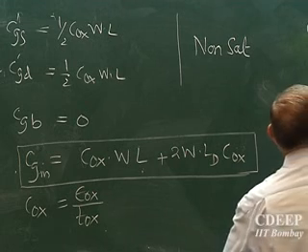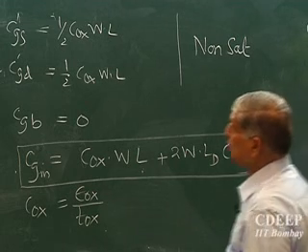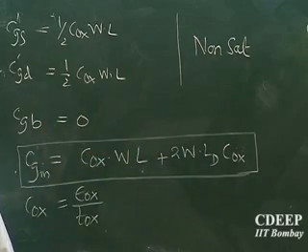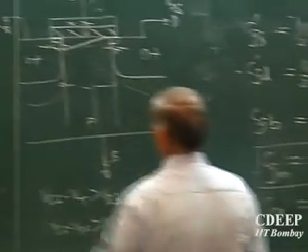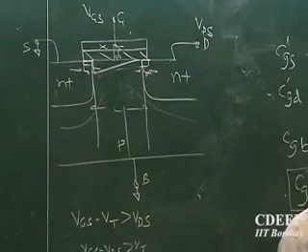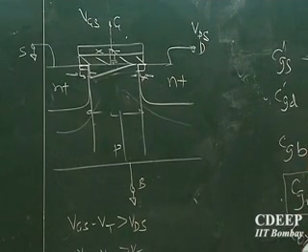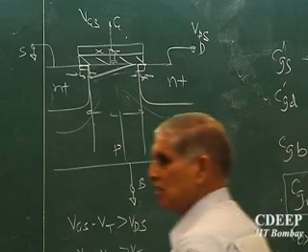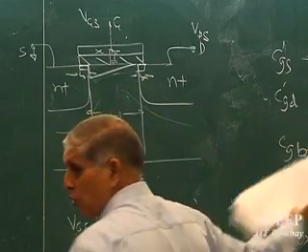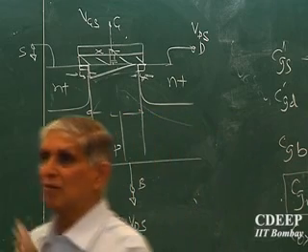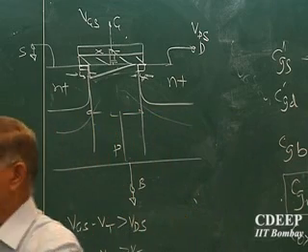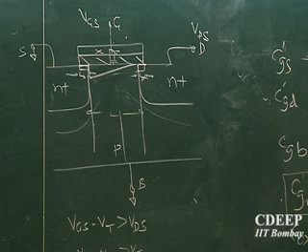In case of saturation, what will not be there? Which capacitance is only available on the drain side? Overlap. But the net capacitance now is ascribed fully to the source side, and one says in case of saturation,